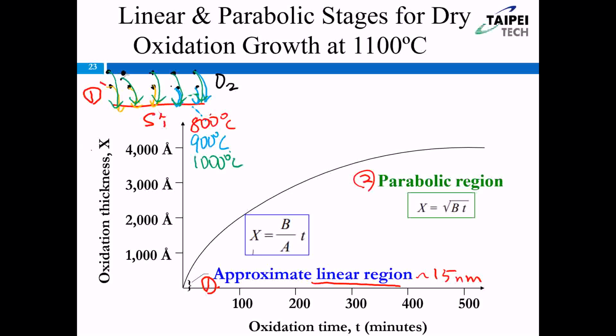I mean, when the oxide thickness is smaller than 15 nanometers, just at the first moment, the temperature is very important at the beginning of the oxidation. So we mentioned this mechanism, we call it reaction rate control.